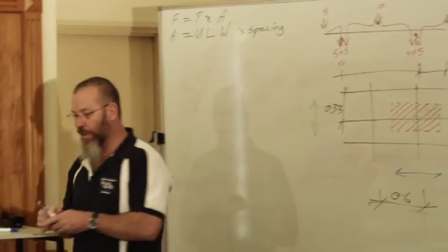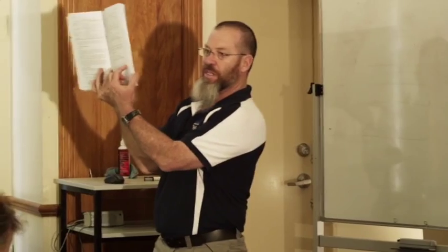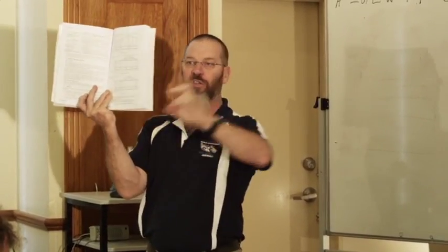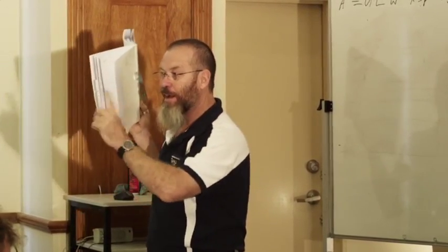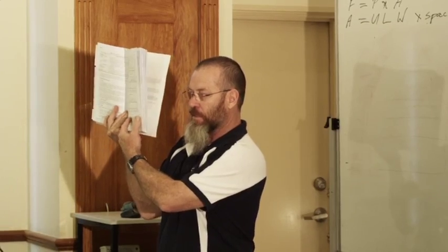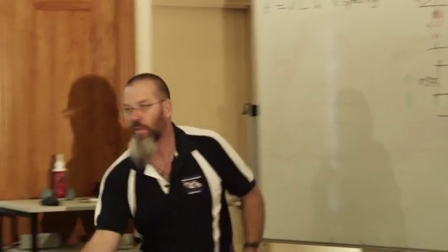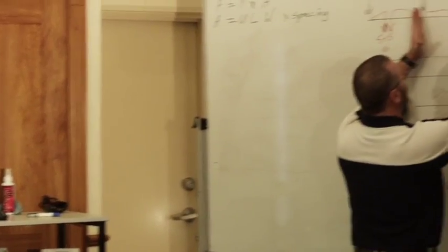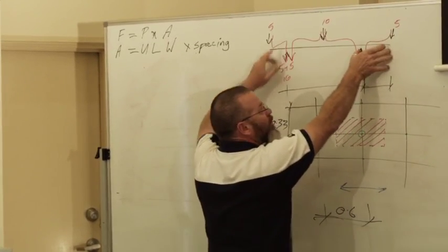Have a look at that bottom diagram on page 171 or 169, depending on your book. Look on this side of that diagram. Can you see those ULW lines? It goes from half the distance between the wall frames, or half the distance between connections, plus the overhang. Can you see it there? See how it includes the overhang on the outside? Now apply this back here to this beam. So the load width in this case is that distance there. Half the distance between connections plus the overhang.